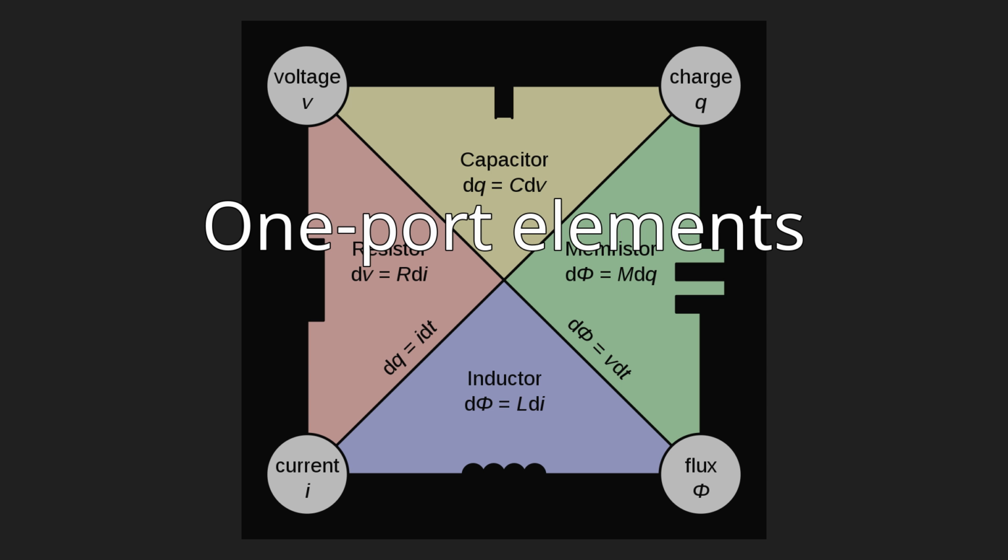Voltage-controlled current source, VCCS, generates a current based on a voltage elsewhere in the circuit with respect to a specified gain. Used to model field effect transistors and vacuum tubes. It has infinite input impedance and infinite output impedance. The gain is characterized by a transfer conductance which will have units of Siemens.